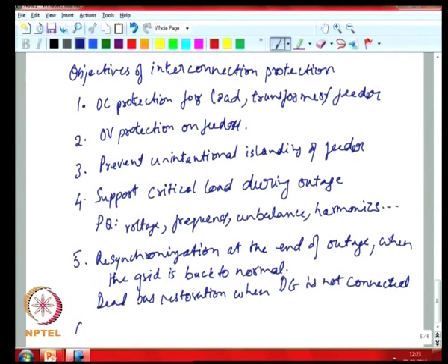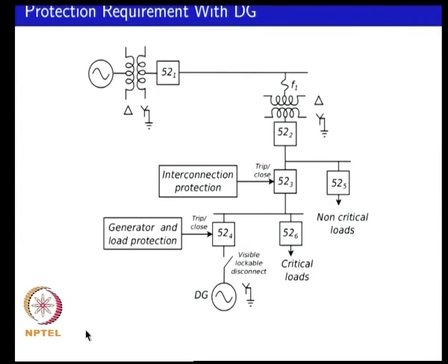Also you might have some additional functionalities depending on the type of sensing that can be done. You might be able to monitor the amount of power now flowing out, the real and reactive power going out into the PCC. So, you might have additional functionalities that could provide additional services to the facility by looking at not just the variables at the interconnection, but additional variables at different locations on the system.